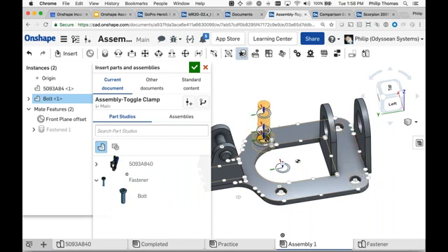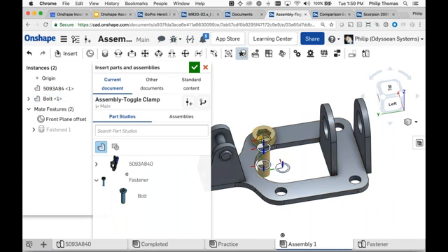So if I come down to the center of this hole, I have a number of things I can control. The orientation of the bolt, I'm going to control with the A key, A for align. I'm going to control the clocking with Q, Q for clock. You can see the mate connectors rotating, but there were also 3 different mate connectors on that bolt. I'm going to use the Control key to cycle through them to get the one that I wanted. In fact, that's the one I want. And I just click to say I'm done with that one.